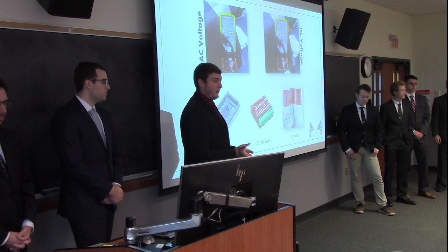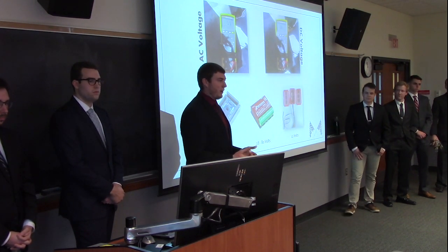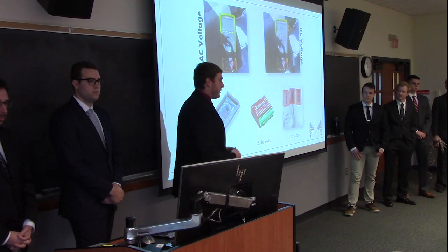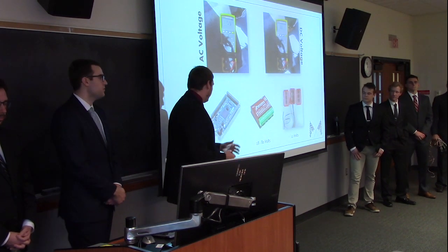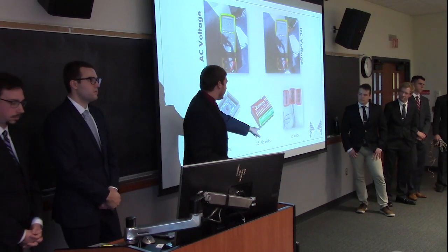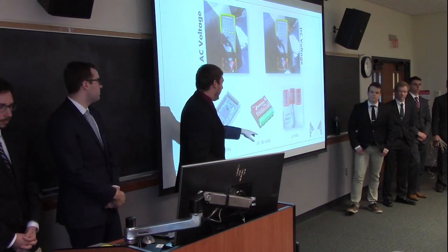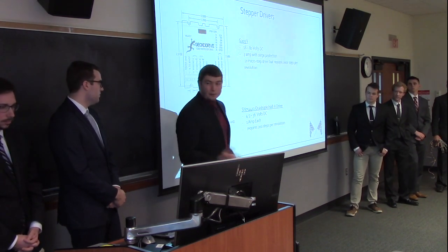And that was at idle speed. And whenever it actually speeded up and we were at full speed, we got around 15 volts out of it. So what this is used to power is going to be the Arduino, like John mentioned before, and then these two things down here, which are our stepper drivers that help drive our stepper motor. And I'm going to go over those right now.